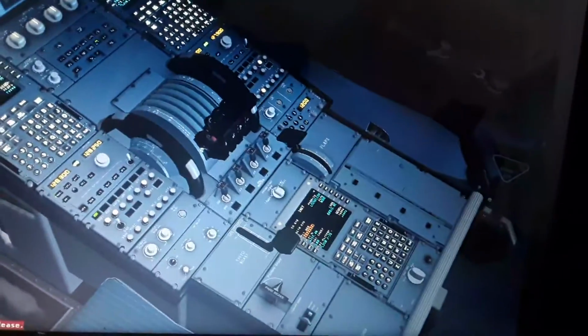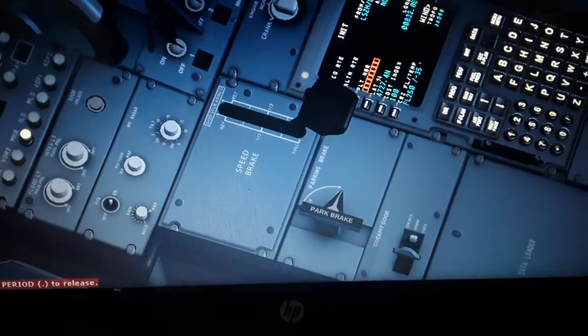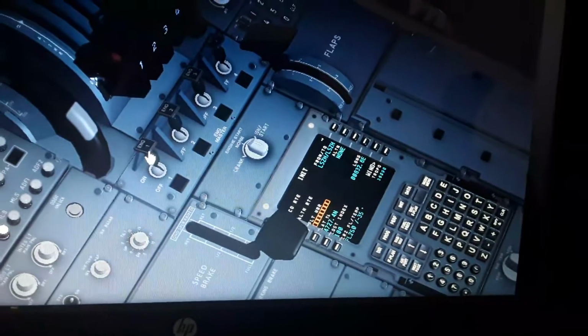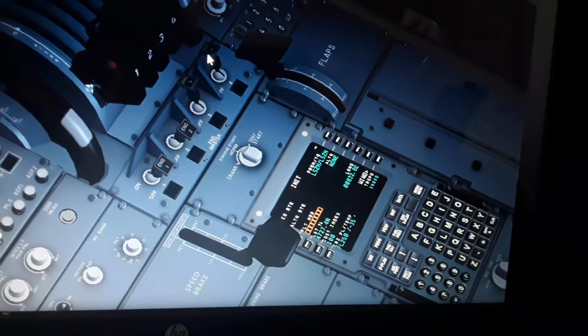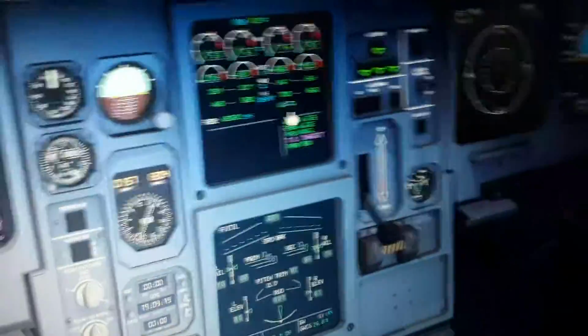So I'm going to show you how to turn the engines off and on. Maybe we have the APU on, so we can actually turn each engine to the off position. You're going to use what they call the engine master switch here and the engine start lever. So I'm going to turn them off. So we have no fuel supply in the engines now.